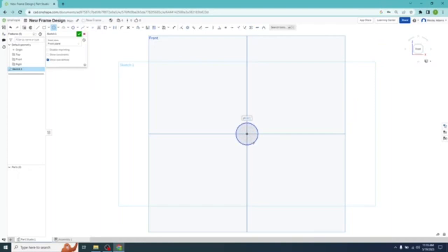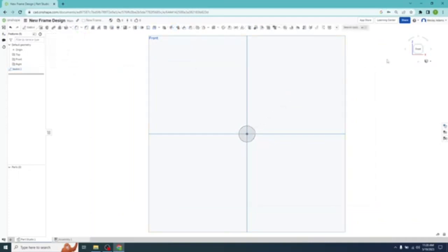So try to envision a 1/2 inch aluminum tube. So I just dragged that out, and then I released the left button. Go up here to this little tool, this dimension tool. I'm going to click on that with left click, come down, and left click on the outside of that circle. I'm going to drag that away. This is where we're going to give the dimensions, the diameter of that tube. So let's go 0.5, 1/2 inch. So we want it 1/2 inch. Back over to our view.